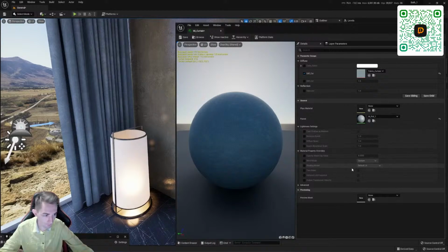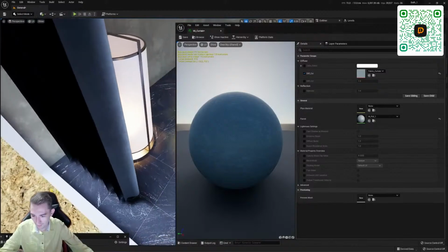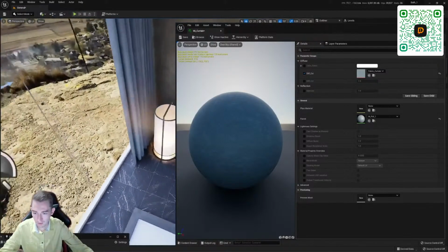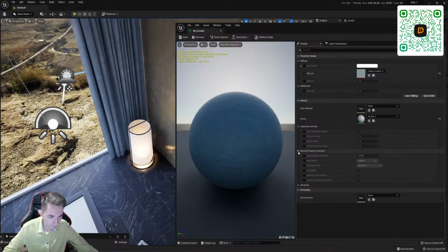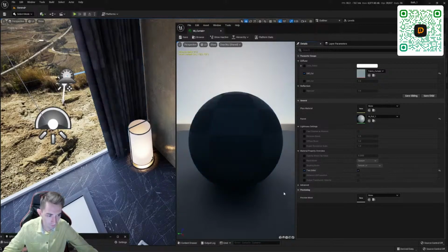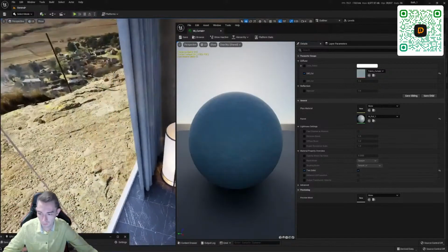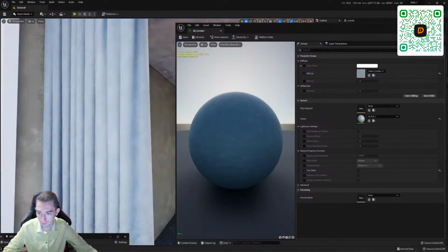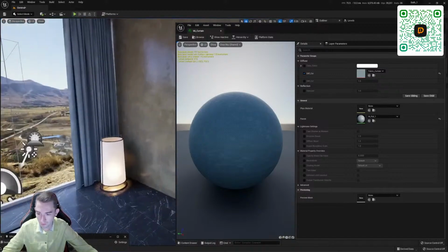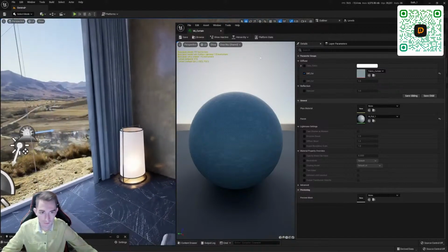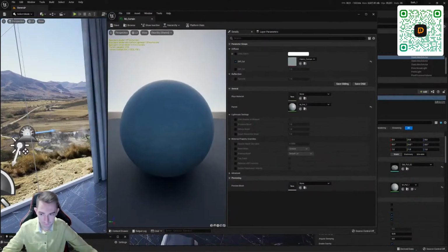Then here we have to enable the material on both sides, if it is visible from both sides. It is easy to do, you can even do it in the instance. We go here to the material properties scroll, and there is a two-sided tick. Turn it on. Let's wait a little and now we have a curtain on both sides. I'm going to turn it off now, because it eats up resources very much. Therefore, we try to use fewer of these options with double-sided material.